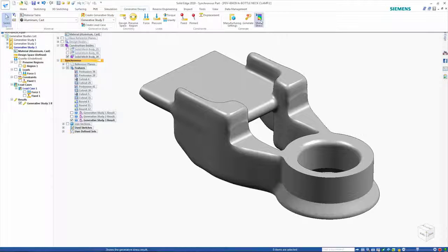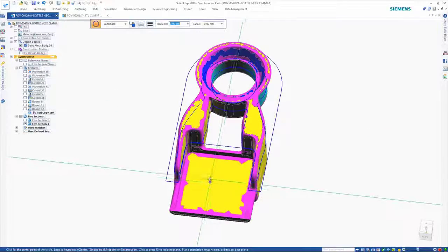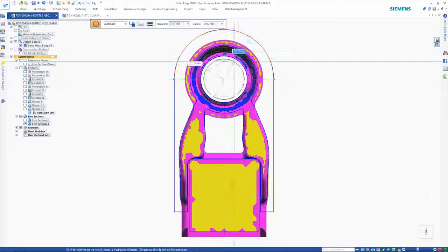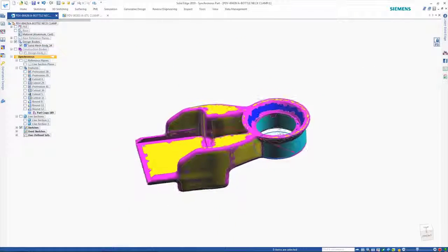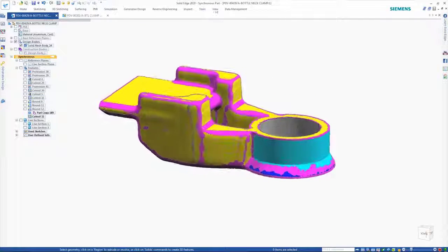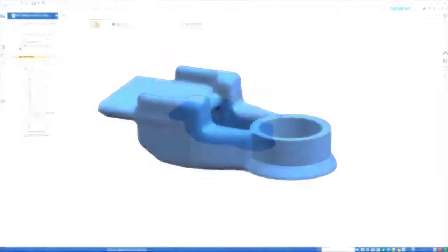The result from the Solid Edge generative process isn't just an idealized shape that needs to be reverse engineered. Siemens convergent technology allows the use of mesh data downstream. Now Solid Edge will recognize planar and cylindrical faces on the mesh body. Here, a simple sketch on the underside face is used to create a cut to increase the size of the bore. The ability to combine mesh data with regular modeling features is unique to Solid Edge.